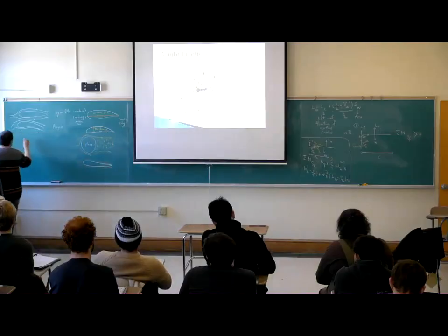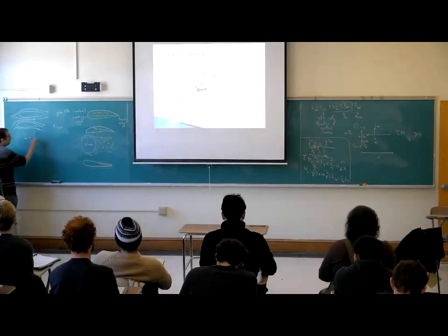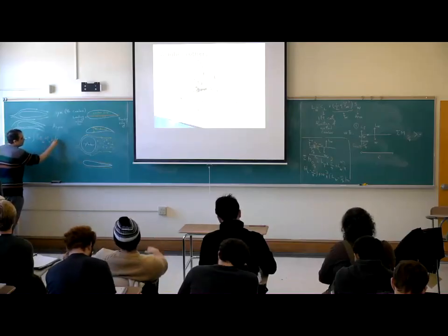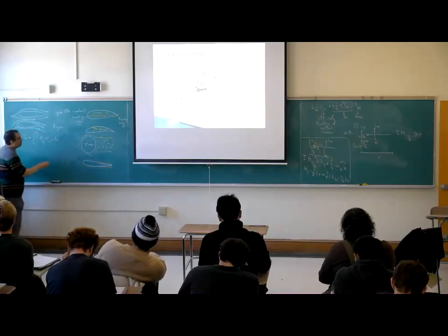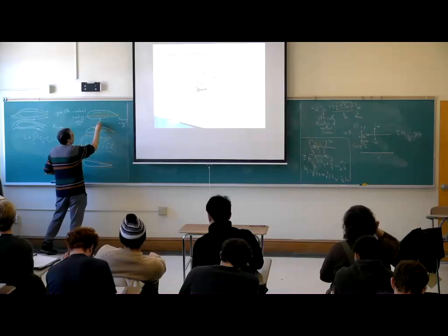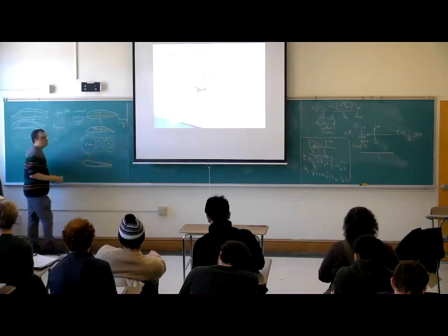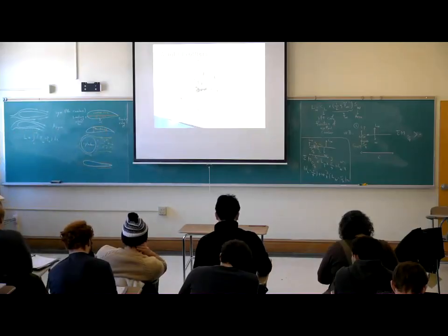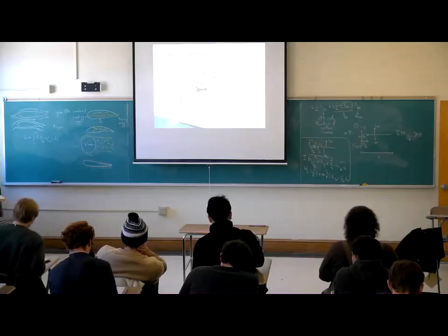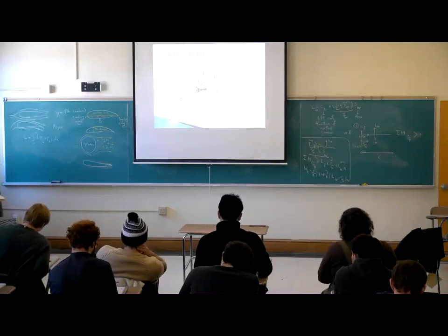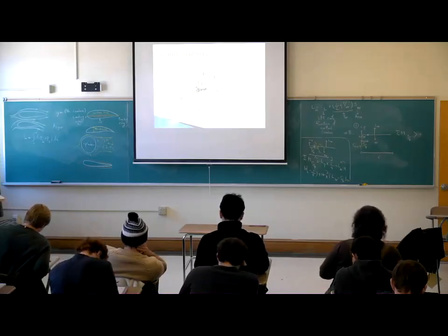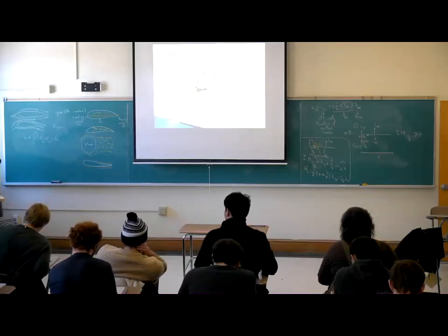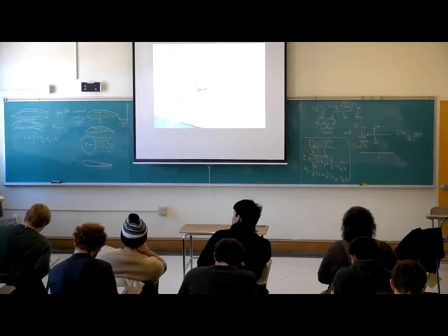So lift is this equation: integral of P lower minus P upper dx from 0 to C. The length of the chord line is shown by C. So if you want more lift, create higher pressure on the bottom and lower pressure on the top surface.